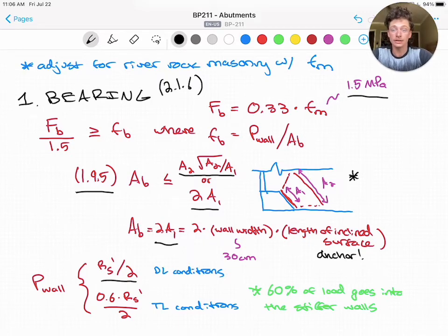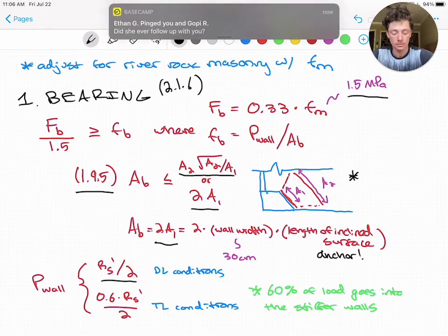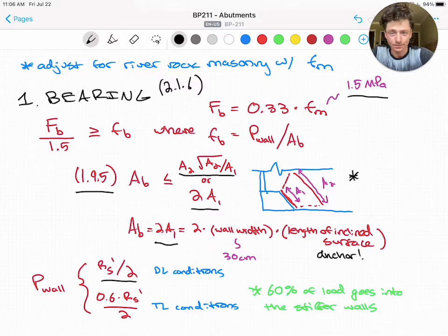For post-fill, after filling the ramp and finishing the abutment, this is not as simple as distributing force based on the area, ramp walls versus ramp fill, because the materials have different stiffnesses. Stiffness is a measure of resisting deflection when force is applied. So stiffer structural elements will take a larger portion of the load, and usually loading is distributed based on measured stiffness. But due to a variety of unknowns, including workmanship and air voids, we can't determine the stiffness of each material.